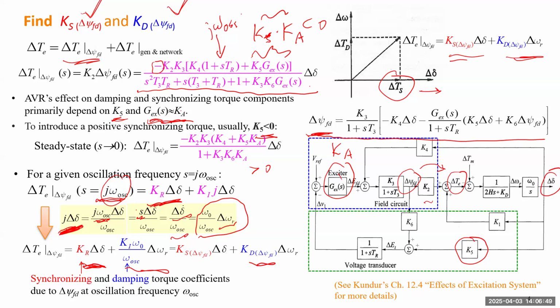I have a paper from a few years ago. I followed exactly the same approach to study the cause of the subsynchronous oscillation caused by a wind farm. Even though that's not for a synchronous generator, it follows exactly the same idea. Because for the wind farm, the oscillation can be caused by some component, and you design a transfer function similar to that one. For a generator, that transfer function is from the angle deviation to the electric torque, electric power.